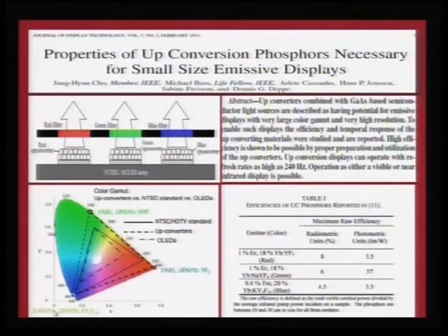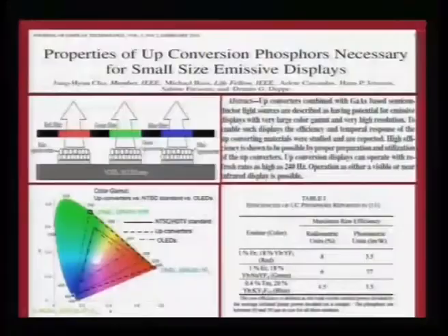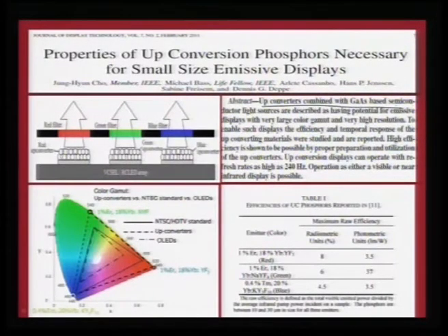And there are also other examples of up conversion, not necessarily the examples that I showed there. Here you are using a combination of gallium arsenide based semiconductors, and in combination with this phosphor they can do an up conversion. As you see here, this is your gallium arsenide based panel, and here you can put your phosphor, and then you can get, through suitable filters, either red, green or blue colors.